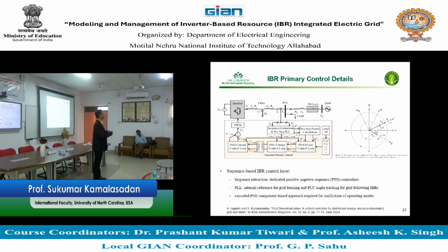That is called fault contribution. Fault contribution meaning you are contributing towards the fault to limit the fault and maintain the current by this metal winding. The bad news of the inverter is that there is no winding, which means you are not able to contribute towards the fault. So fault contribution for the inverter is basically very less, or the fault current that can be drawn.